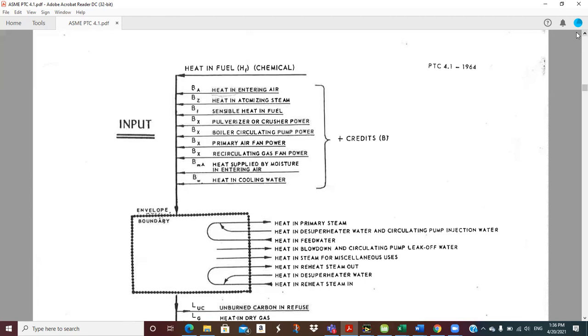So any moisture we're bringing in, that's water vapor. And water vapor, even in the atmosphere, is probably someplace around 1,000 BTUs a pound coming in. So that's energy into the control volume. And then if we have any cooling water, it has some temperature where it enters the control volume. So that would be heat coming into the control volume as well.